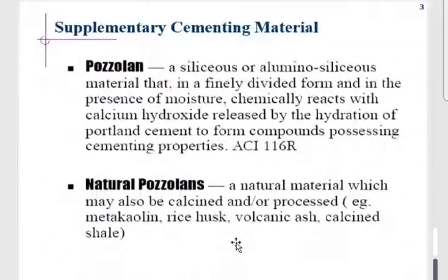micron. So once we go for the binding ability of the cementitious material, there are two things. One is physical characteristic and the second one is chemical. So talking about the chemical reaction, this calcium hydroxide is accompanied by the siliceous compound that is available within the cementitious materials, and it reacts and makes a secondary calcium silicate hydrate.